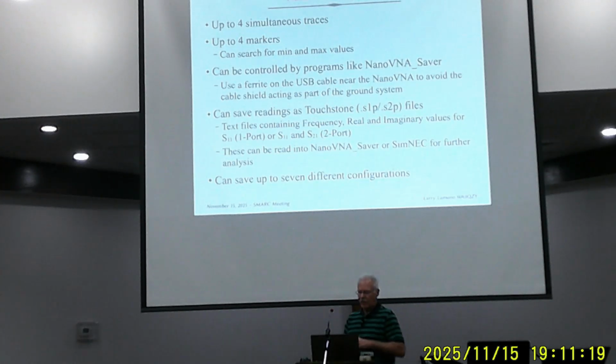It's really powerful to be able to take those readings that you take with this and move them into the other programs. So once you set all this stuff up, you can save up to 7 different configurations on here. So say you're testing a 20-meter dipole, and you set it up and you calibrate it and do all this stuff, you can save that. So if you want to go back to that, you just simply call that back up, and all those settings will be there. You don't have to go through this every single time.